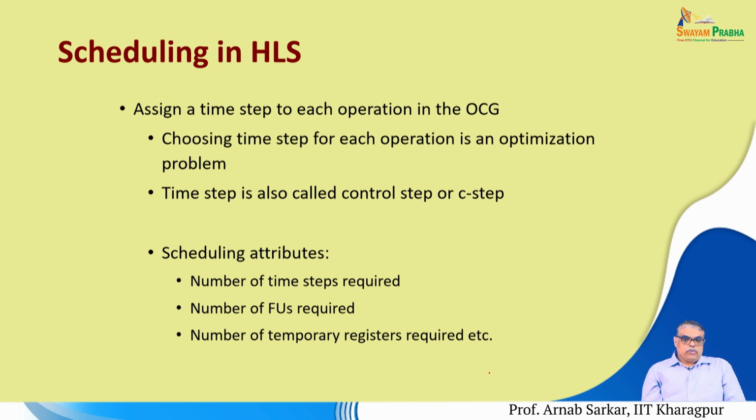Okay. Now, we go deeper into the scheduling step. So, we saw the overall operations within high level synthesis. We saw that we take the application, obtain the control flow graph, generate the master controller, go into the basic block, schedule operations within the basic block. After scheduling, we do an allocation, we do a binding and obtain the final timed master controller, and after looking at this introduction, we will now go into scheduling in more depth.